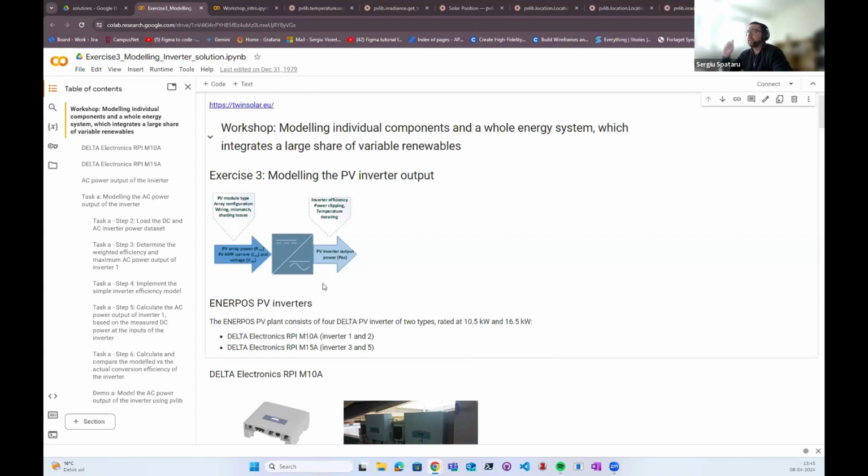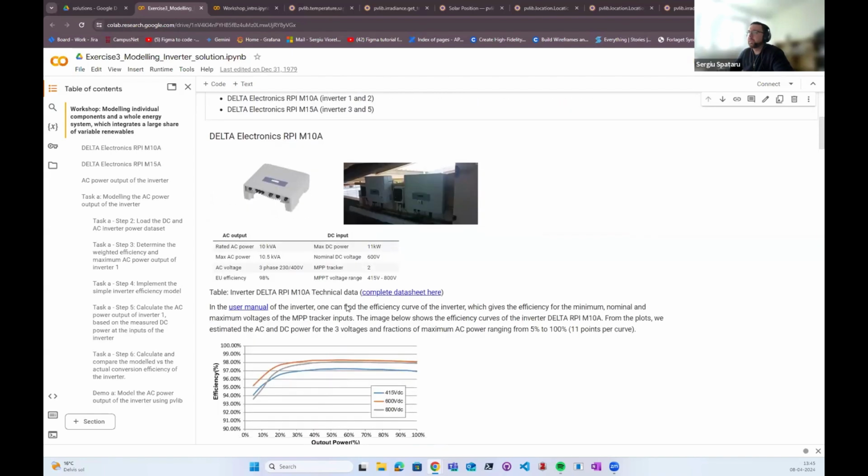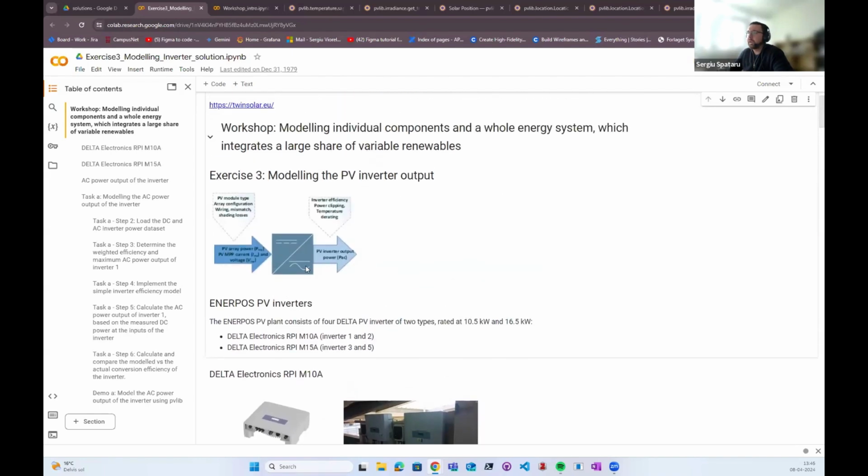inside the inverter, and there are two major types of losses that can occur. The first one that always occurs is the conversion losses. So a power converter has some efficiency, which is variable. It's not an ideal converter, there are always thermal losses and switching losses occurring inside the inverter. How many occur will depend, as we'll see, on several factors.